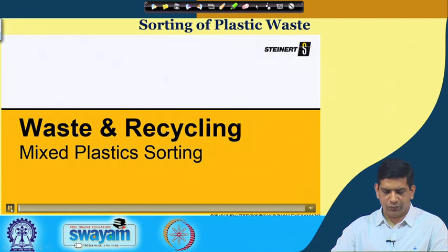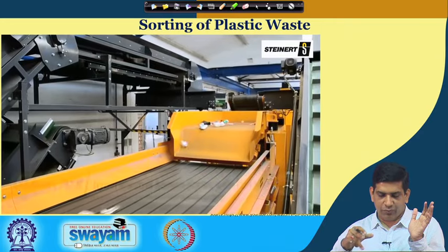In terms of the container system, you see that mostly now it is your plastic. So, it is a hyperspectral sensor sorter. What this sensor sorter does is take out the clear PET fraction. The first task it does is to remove this clear PET. Any clear PET bottle, it is removing that, and then again it is on the conveyor belt. In these plants you see lots and lots of conveyor belts, things just moving around.